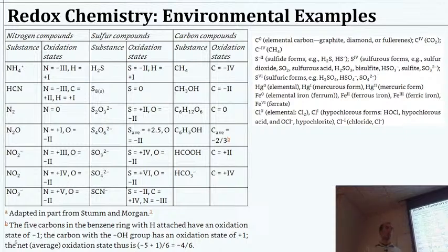This would also be true of other metals that are oxidized easily by chlorine. Suddenly, a lot of the chlorine experiences what we call instantaneous demand, and it's gone. It's spending its effort oxidizing things, so we could then calculate, given some amount of sulfide, how much extra chlorine we need. So there are reactions like that we see pretty commonly that can be quite important.